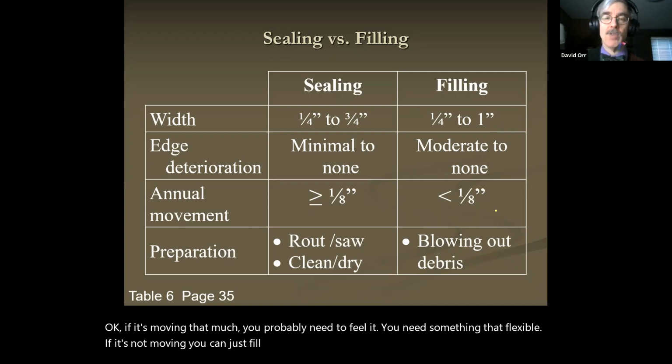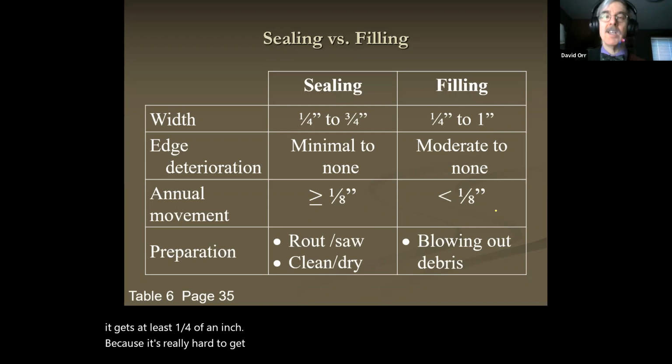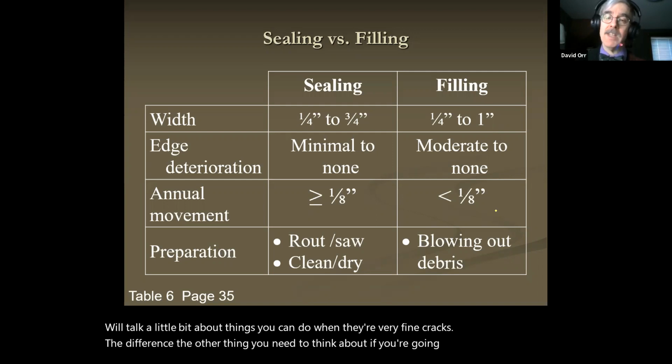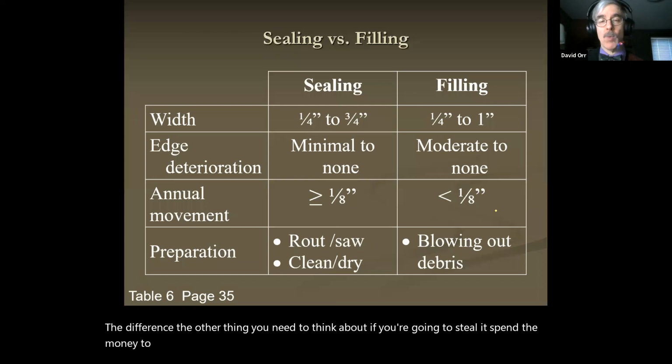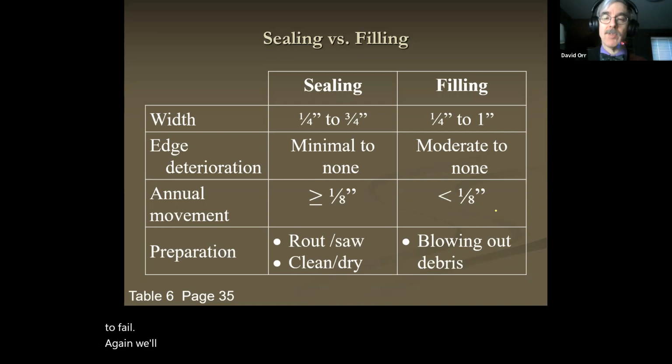Okay? And you'll notice there's no point in sealing or filling until it gets at least 1/4 of an inch because it's really hard to get material into the crack. We'll talk a little bit about things you can do when they're very fine cracks. The other thing you need to think about is if you're going to seal it, spend the money to route it out or saw it out to make it wide enough to put a reservoir to give you that room for expansion. Because if you don't have enough room for expansion, your seals are going to fail. Again, we'll talk a little bit about the exceptions.